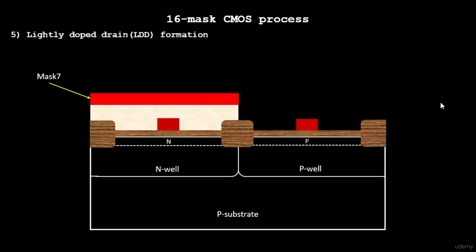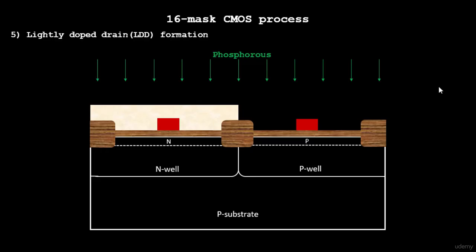Doping concentration was maintained by the p-type and n-type impurity implants that we did in the previous steps, and the oxide capacitance is now controlled by the oxide thickness, which is maintained over here. Okay, so two parts have been taken care of, and now the final step is where we have to look into the gate formation. So the steps are pretty simple.